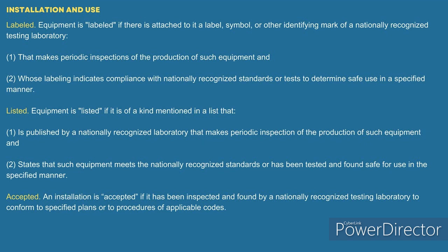So let me ask you this. If I have an AC unit out there, and the manufacturer says no GFCI protection on this, guess what? They had a listing and labeling. It's been tested to say that equipment operates just fine. There's no hazard to personnel. The NEC does not have the right to come in and require GFCI protection on that unit now.